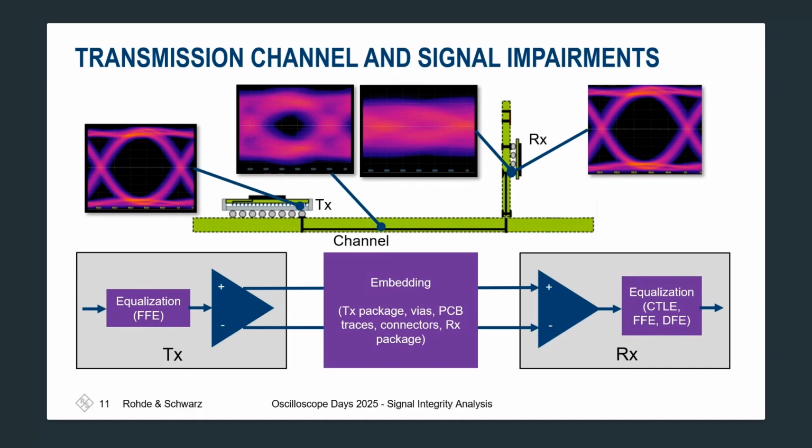And then you might have even seen on the transmitter side that we also have some equalization that can be done there, which is FFE again, but this is then a type of pre-distortion where we can try and anticipate the distortion that would happen within the channel and then cause additional behaviors on the front end to then add extra rising edge on top of it so that we can inhibit and displace what the effect would be through the channel.